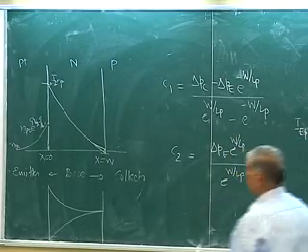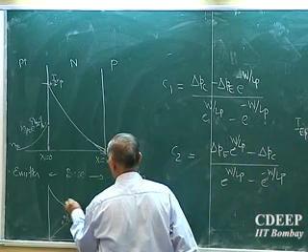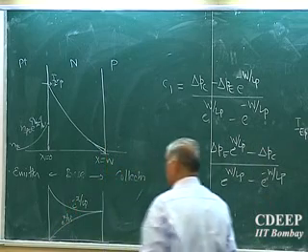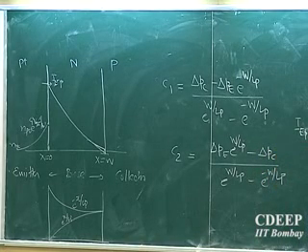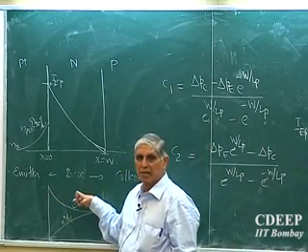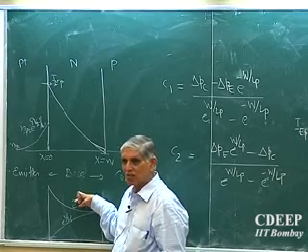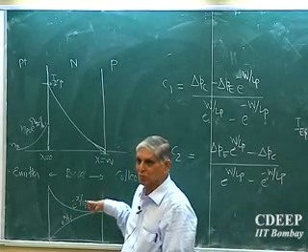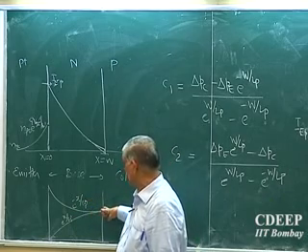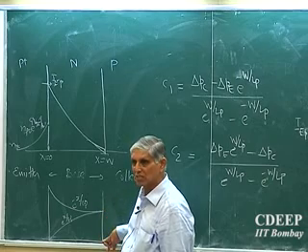This is e to the power x by Lp, proportional to this e to the power minus x by Lp, and if I say delta Pc is 0, one can see very clearly this will be only delta Pe dependent. I repeat, what did I say? If delta Pc is taken 0, then the two terms must be such that when I subtract them, the value should be the same, so that the net current is 0 at x equal to w.